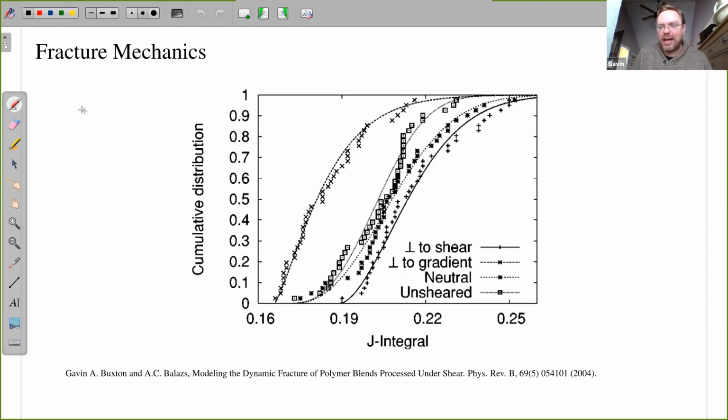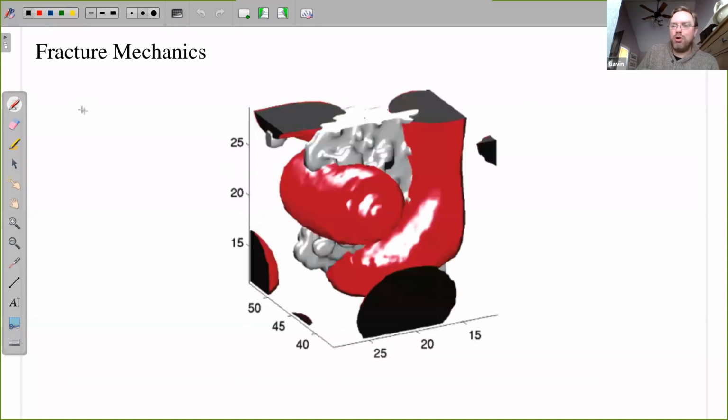Just to say that, in terms of some of this fracture work, you can calculate things like fracture toughness and the J integral and some of the things that engineering fracture mechanics like to see, even though from a physics point of view they might not always be the best things to consider for your system. They're the standard things. You can get those out of these models too, which is something that you would more associate with finite element method.